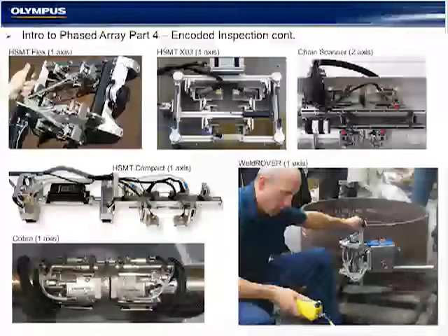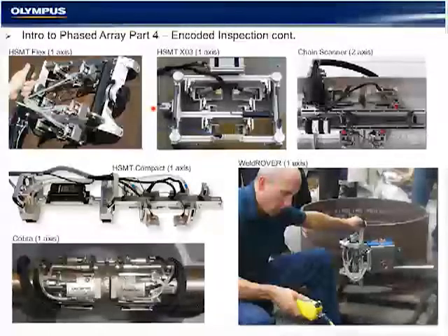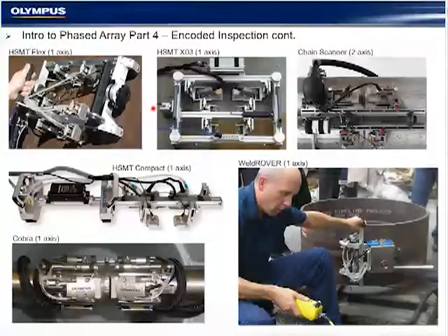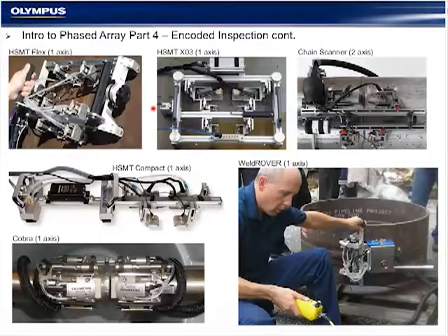In the encoder of the X03 that you see here, it's a simple wheel that converts a clock trigger to distance. They're typically a quadrature type encoder, and they would have a resolution that tells the software that for every number of pulses received equals 1 millimeter or 1 inch. They can be calibrated, and in general, the resolution, once determined, if there's no damage to the scanner or wear, stays very accurate.